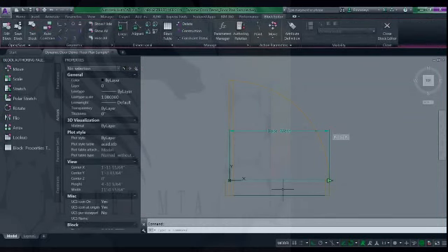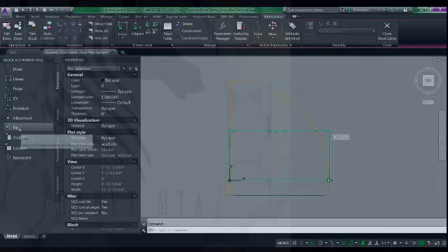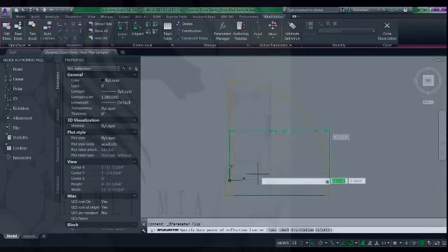And then, hope everyone's still with me. We're going to add some flips. So we're going to want to add a flip to either have our door flip to the right or flip to the left, and have it flip into the room and out of the room. So what we want to do first is set up a parameter for our flip. So I'm going to go to our parameter, select flip, and then my first flip, I'm going to have my door swing either to the right or to the left.